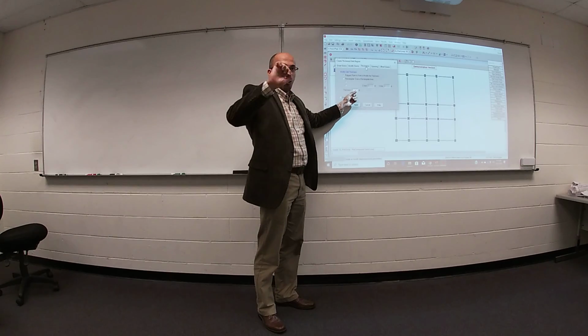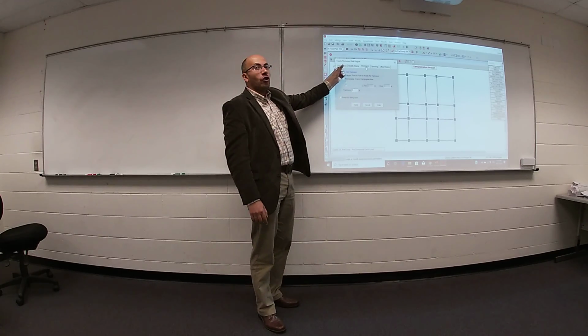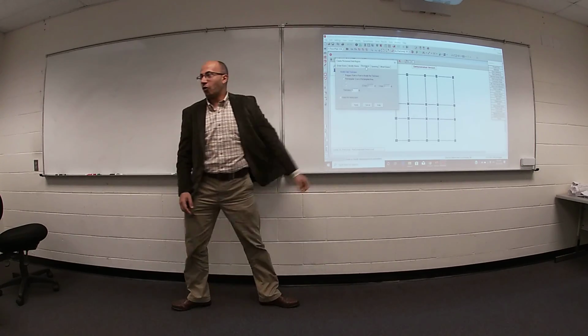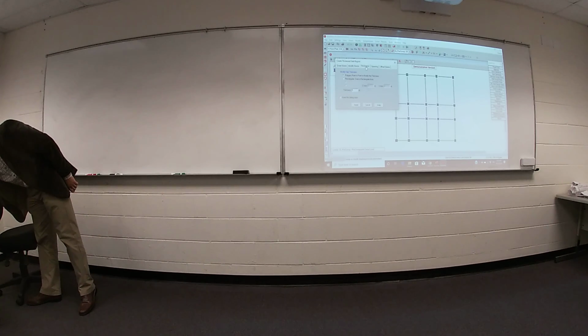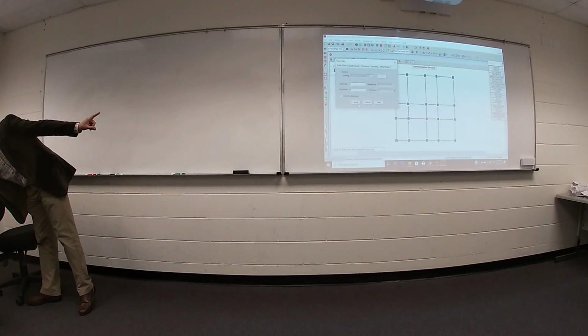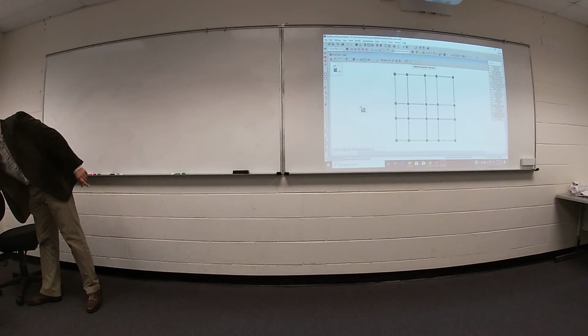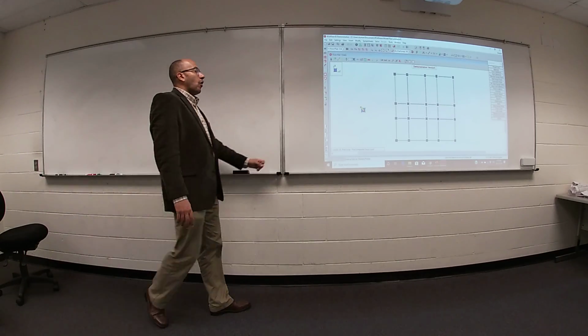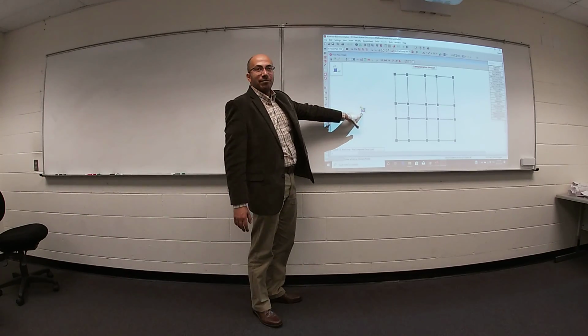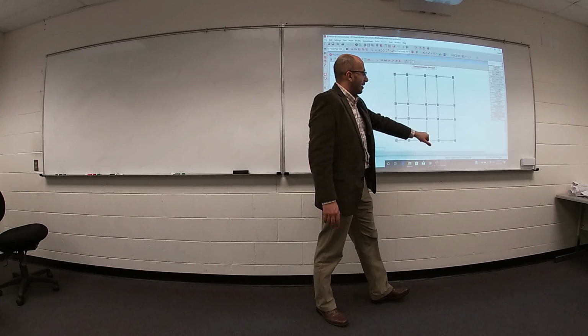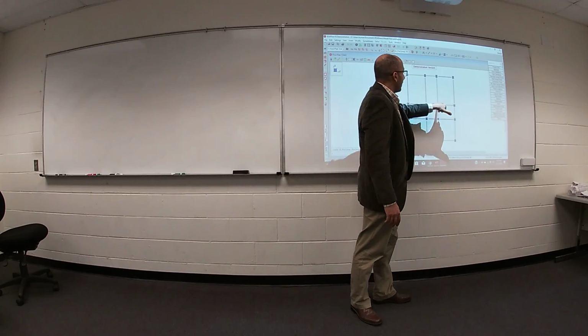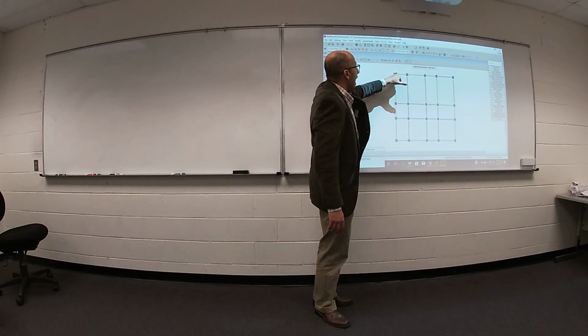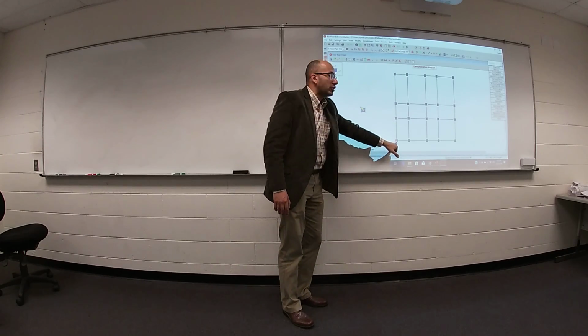Right now I would like to draw. Please go back to draw slabs. Then apply. Once you did apply, you are ready to draw your slab. Just click, click, click, click, click, click, and go back to the first corner.